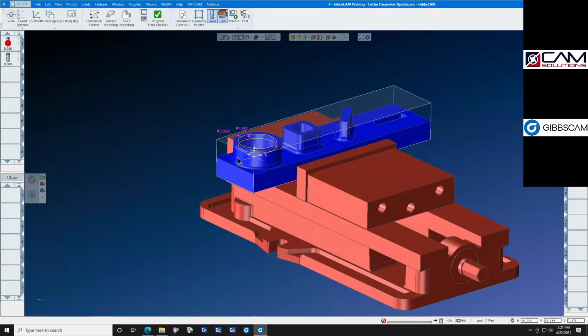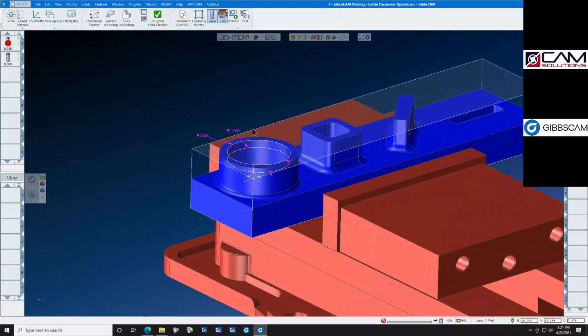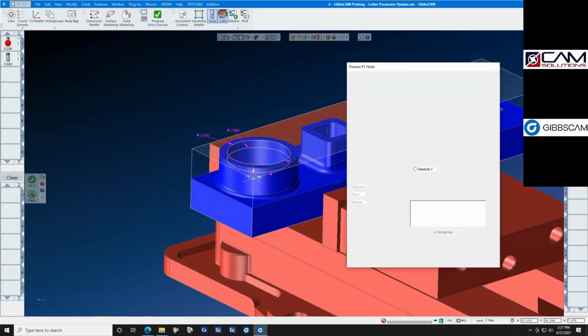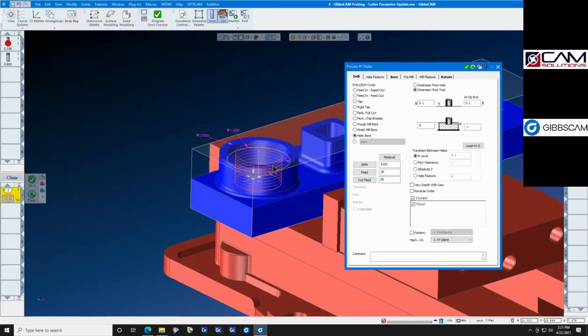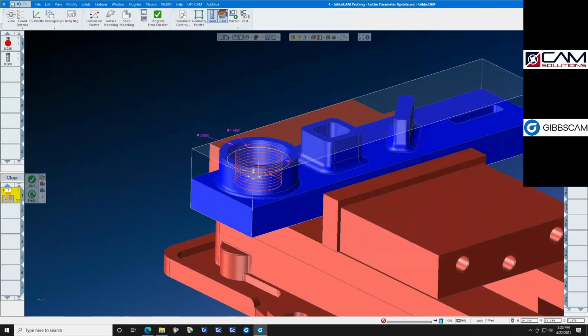So here we are. We have this bore. This bore is 2 inches in diameter, and we have roughed it out, and we have taken a semi-finished pass here in op 1. In op 1, we have a semi-finished pass, and we have left 5 thousandths inside of the bore on either side of the bore. Now with the probe, we put the tool away, and that's our finished tool. We did a semi-finished pass.